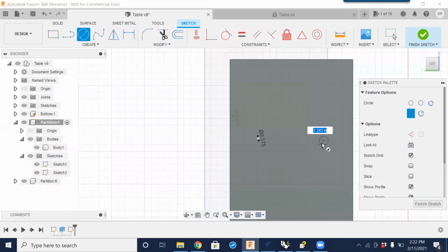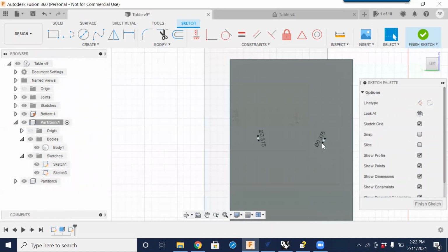And again, feel free to ask questions. I know this is like some of what we went over last week, but we have new folks here, maybe listening just to seeing sketches. So I've got those 2 circles drawn. I want to constrain those, and there are several ways of doing this. I like to use reference lines, or what do they call them here? Construction lines. I've turned the line type on to be construction.